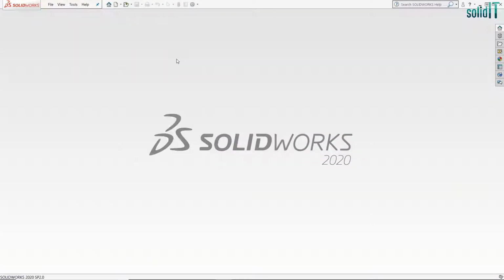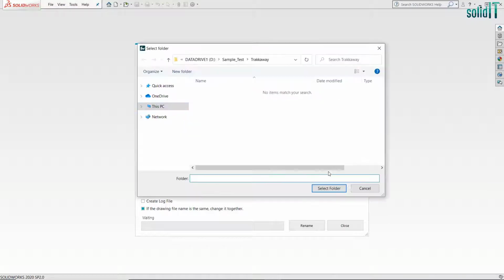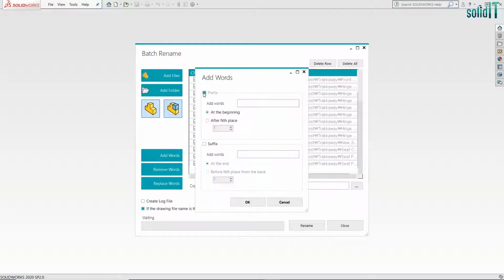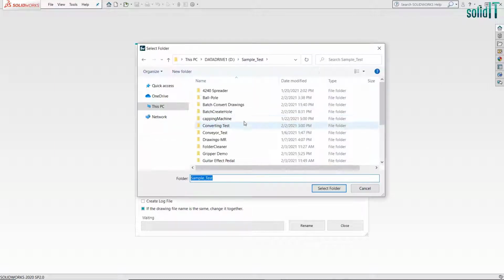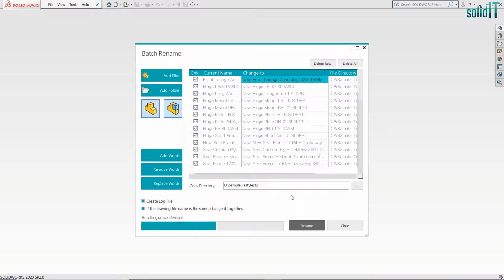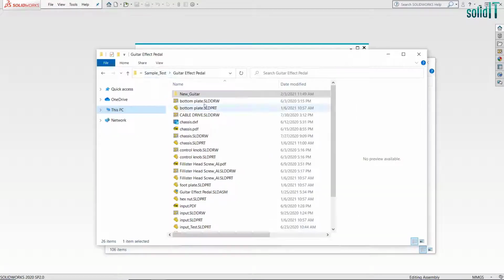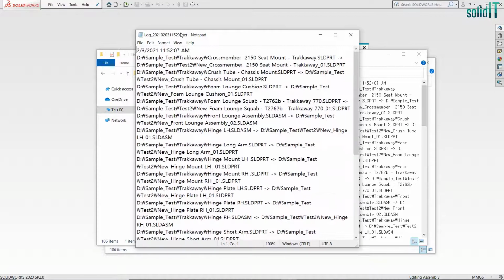When renaming SolidWorks files, managing the names of reference drawings is difficult. Frequent errors occur because reference relations get damaged easily. By batch rename, however, you can rename files and reference drawings without missing references and minimize the time consumed managing files.